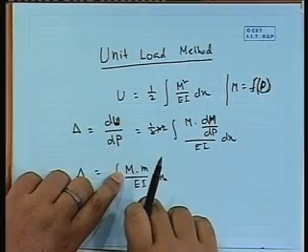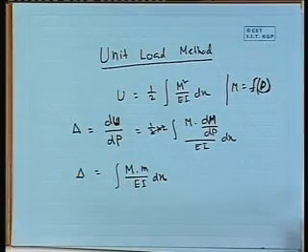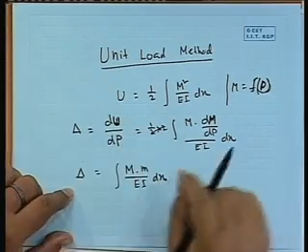Then segment-wise, capital M small m divided by EI, we integrate, and if we take the contribution of all the segments, we will get the deflection at C.